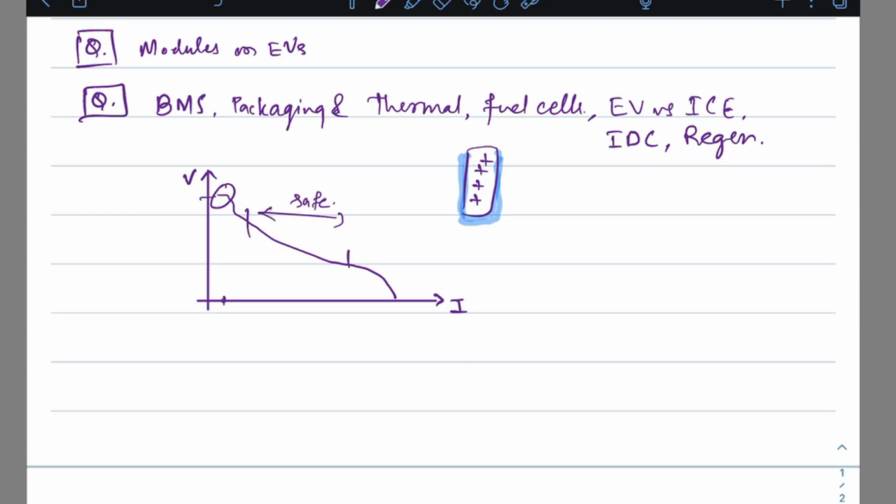The basic idea is that your engine will not give you peak efficiency at all the RPMs or at all the speeds. Then you need something which will get you what you want at the wheels in terms of torque and speed, but also keep your engine operating at the best of its condition. So roughly around 3000 RPM.